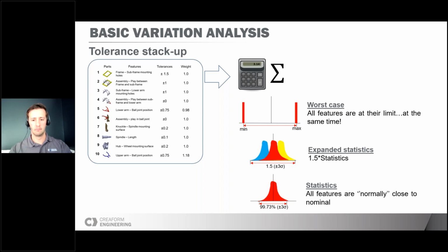Let's say PolyWorks will allow you to make Cpks and a kind of statistical measurement. This is really nice theory, but sometimes it gets to the point where you ask, do I have any data? How can I select the 1.5 for my expanded statistics? Well, you have to know a bit the bias you have on your different manufacturing processes, and then measure your components using different types of equipment. Metrology equipment will help you define some certain bias.